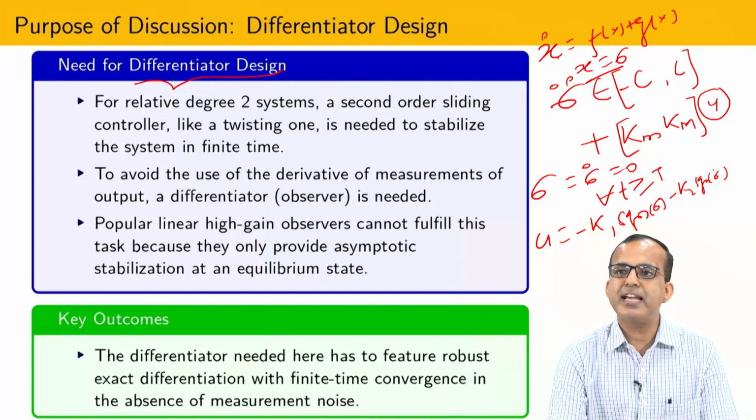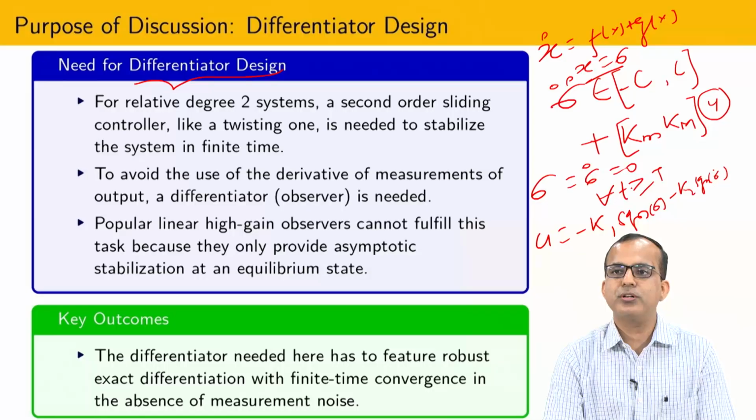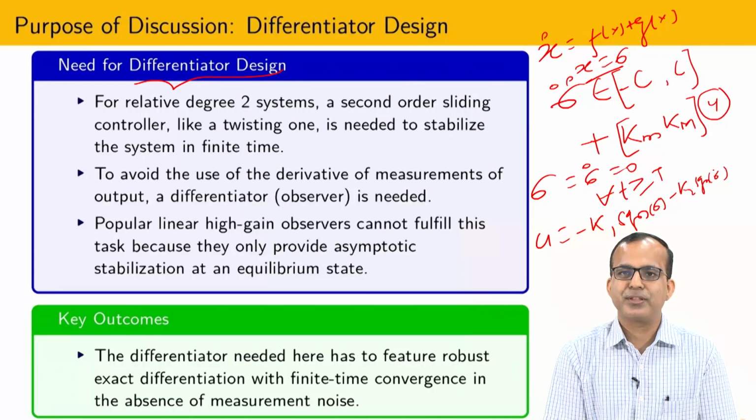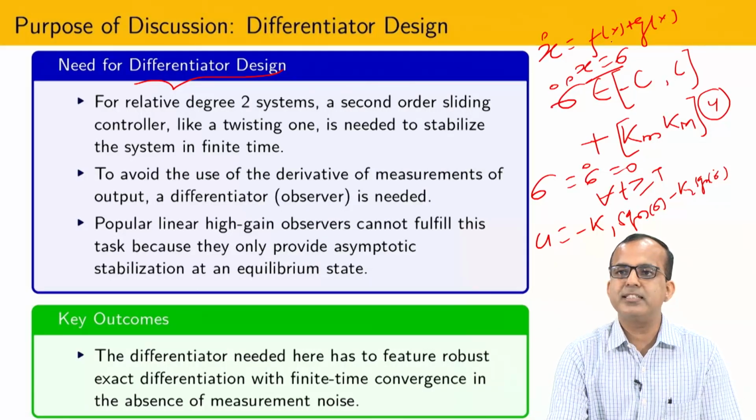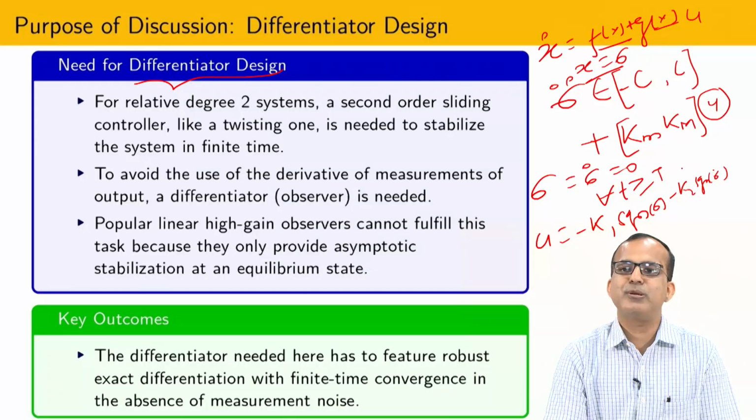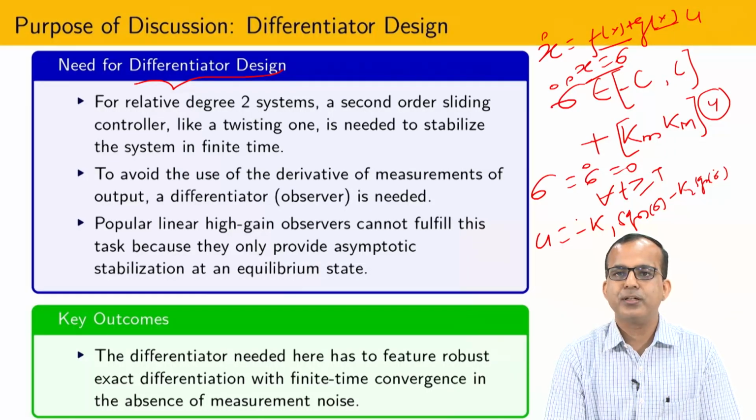If you have an exact mathematical model, then constructing sigma dot using an observer is very easy. You can apply the Luenberger observer if there is no disturbance. But most of the time, since I have a nonlinear system, it is affected by disturbance. So one way is to construct some kind of differentiator such that you can obtain sigma dot from the measurement of sigma.